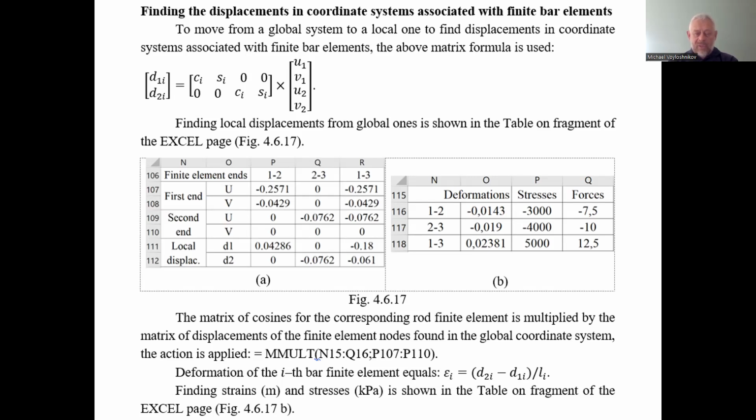The first step of the use of the finite element method is the transformation of all distributed load acting on the mechanical system to the forces applied to the nodes of the connections of the finite elements within the discrete model of the mechanical system.